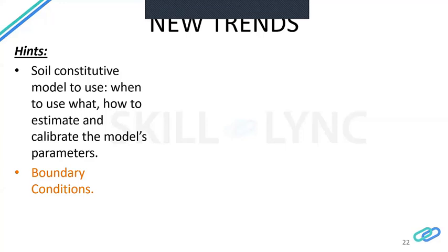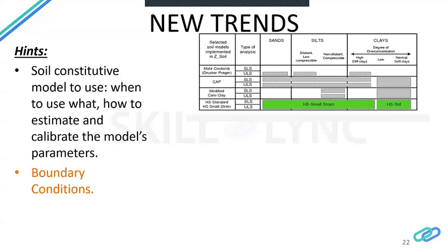But in the geotechnical or the soil finite element model, you have to extend your model well beyond your raft foundation or your foundation system in the three directions, X, Y, and Z, in a way that does not affect your results. The amount of this enlargement will depend on the soil constitutive model you are using. As a good and quick guideline, you can refer to this table.